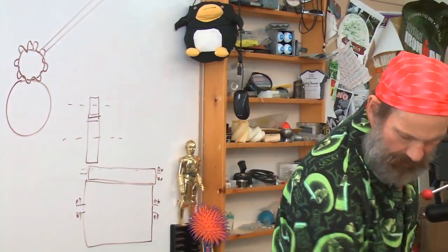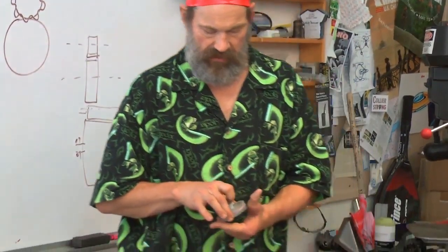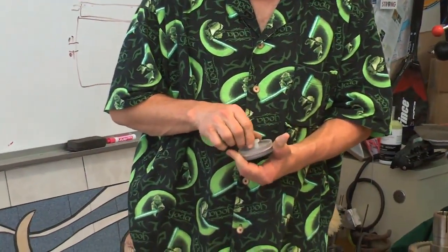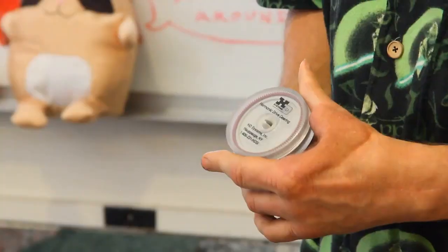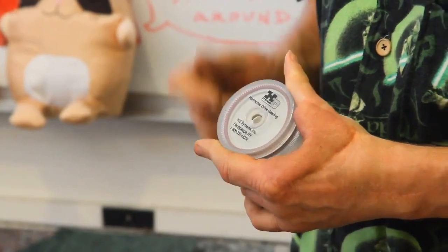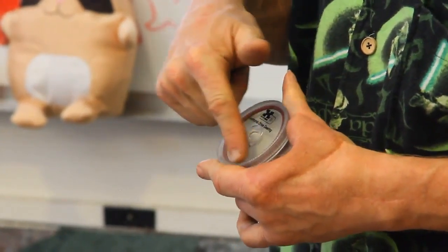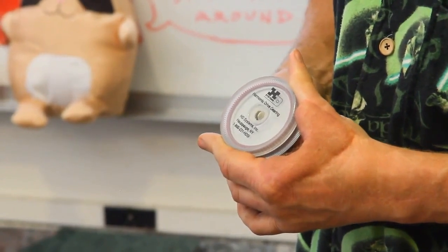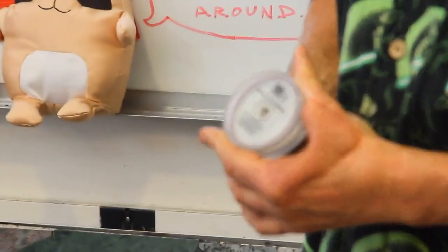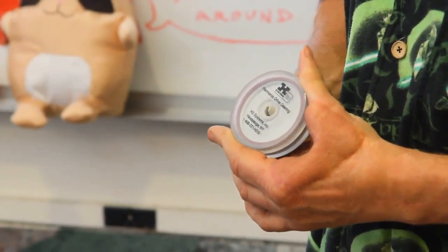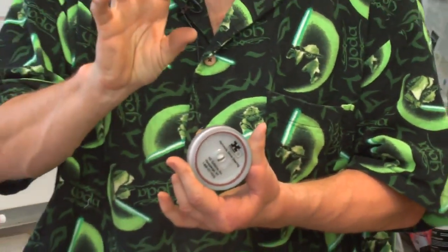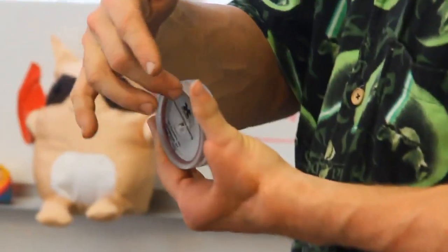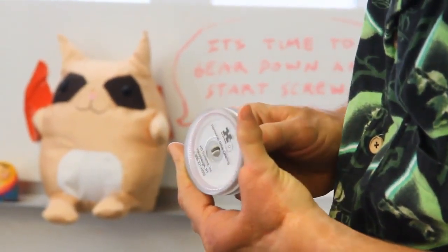And one popular way for epicyclic gear trains is what's called a harmonic drive. And in a harmonic drive, you can see here, what it uses is flexible elements. The red element here is called the flex gear. And as the wave generator, which is the part on the inside, moves, it rotates and it deforms the flex gear. And that deformation actually allows the gear teeth to be pushed together so they do actually engage all the way. And you don't worry about this eccentricity I told you about earlier because of the flexibility of that flex gear. The teeth are very small, so you get very high ratios.